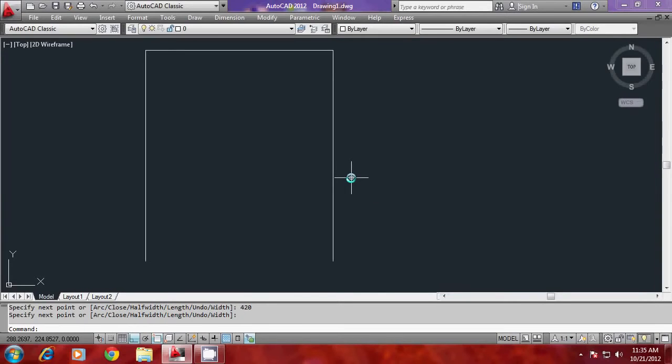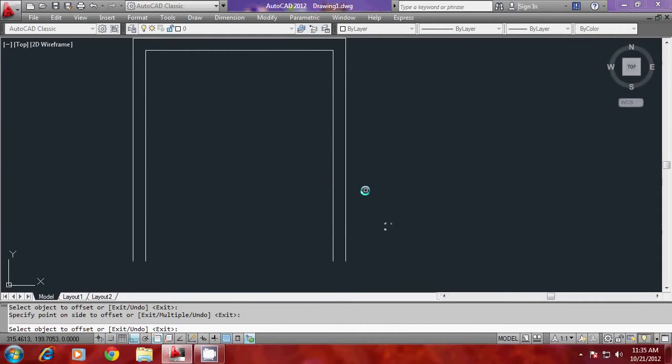give an offset of 24 units outside because the wall thickness has to be outside, because what I said is a clearance dimension. Now I'll connect these two endpoints using polylines, and I would like to join these 4 profiles into a single object so that I'll be able to extrude it. So I'll give pedit and I'll give last.